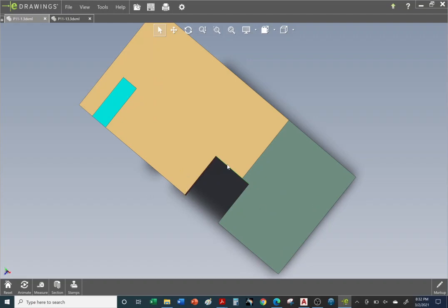Okay, so we're going to look straight down the slot, and look, we have this edge separating the top surface and the right side surface. We do have an object line here that we have to draw, and we're going to draw the opening. But first, let's start with drawing the periphery. So it's a rectangle.